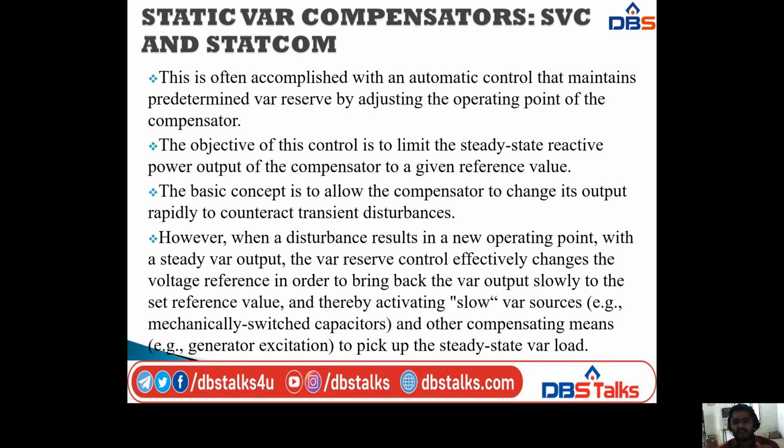But here, the var reserve control effectively changes the voltage reference in order to bring back the var output slowly to the set reference value. That's why we are using this control, this characteristic, and thereby activating slow var sources.